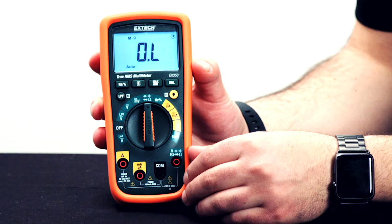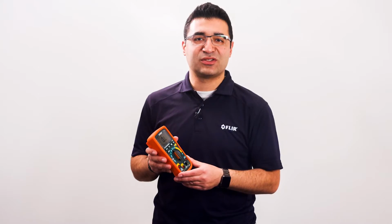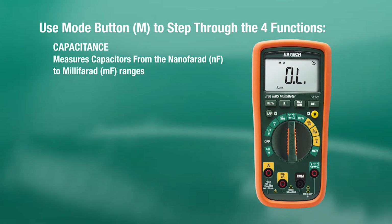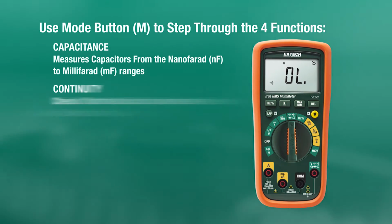Next setting after that is capacitance, continuity, diode, and resistance. To step through these functions in this mode, on this meter you use the mode button, but other meters may vary. Capacitance measures capacitors from the nanofarad to millifarad ranges.